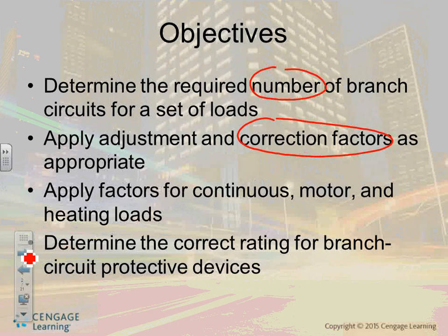When it comes to branch circuits, guys, we always bundle, because it's cheaper. I told you about that one. It's cheaper to put multiple circuits in one pipe like this, 3/4 of an inch. When we bundle them, you end up with more than 3 hots in one pipe or one cable. You can have a cable also with more than 3 hots. Then you end up with derating.